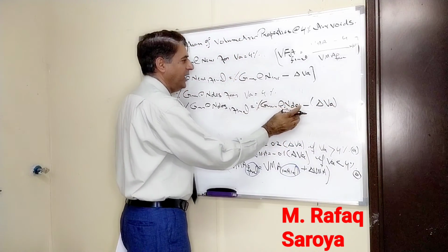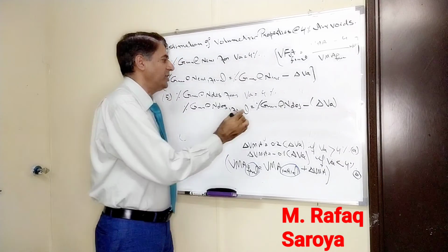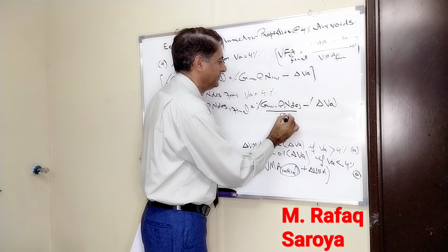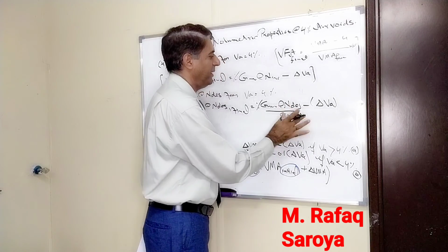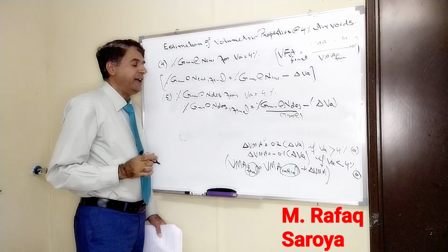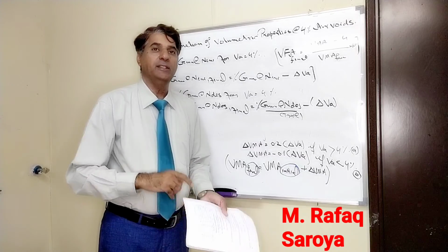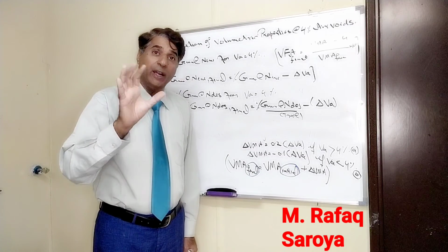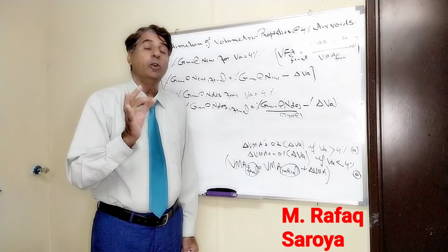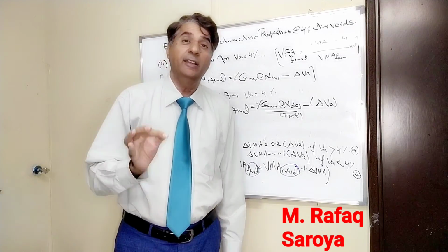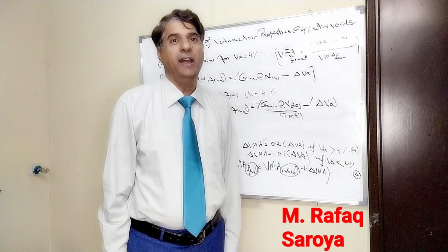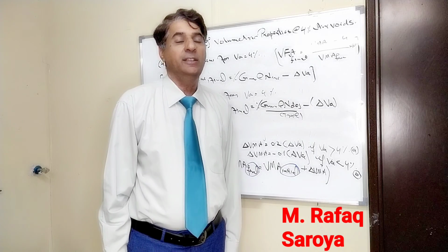This is the value which we have calculated in our initial stage, at the trial stage, just for your understanding, and this is the value coming after the adjustment. So these are our 5 very important properties. With these 5 properties, I will try to explain for each blend how much value is affected when we go for our assumption that air void should be kept at 4%. Thank you for seeing this.